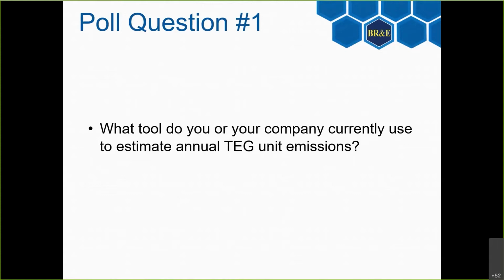Okay, so just got another question. In regards to benzene and hydrocarbon absorption, does the fluid package give different results when using TEG versus DEG? I've seen an empirical study that distinguished between the two of them. DEG absorbs less hydrocarbons than TEG.